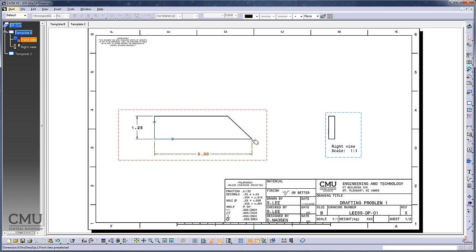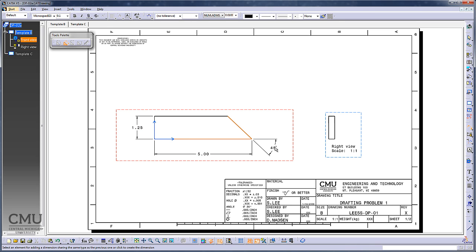I have an angle of 45, but that is a basic dimension. So you're not actually measuring those. It's actually relying on the feature control frame. We'll talk about it later. So I need an angle. So pick the angle dimension and click, and you can see you can create angles very easily.